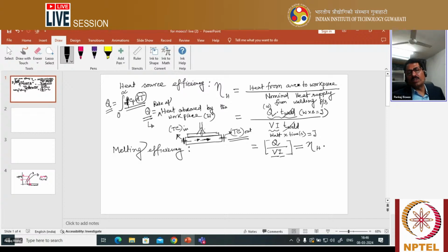It depends actually on surface condition, because laser power loss is very high, as it depends on surface quality. Because laser welding is based on light energy, and light fully depends on reflection phenomena, correct?